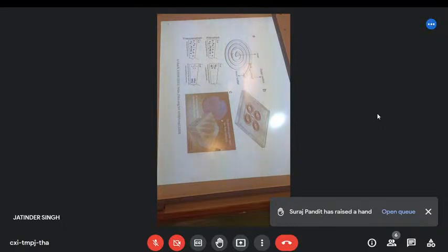Coopers is one of the bit larger microbreweries in South Australia. They had a problem with reoccurring bacterial infections. So they started adopting these devices for separating the bacteria out of their beer brew. They've got stacks of them of 20 or 30 in a row. Don't need to add any other filters. Don't need to add any cleaning. The yeast comes out in one fraction and goes back into the fermenter. The bacteria come out in another fraction and are discarded, which means that they've got much less problems with their beer going off because they can remove their bacteria before they become a significant problem.